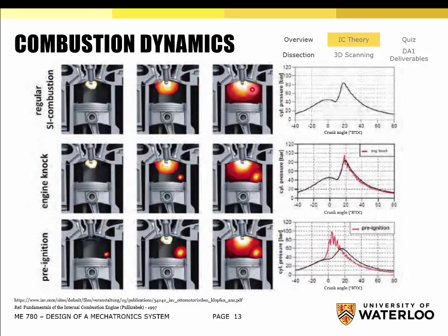But what happens if we have too much temperature, too much pressure, some really poor fuel, or some inhomogeneity in the cylinder? We might have something like this, where there's some rogue event where it's actually igniting somewhere else. Okay, so we've ignited it where it's supposed to with the spark plug, and it starts to increase in pressure and temperature, and what that's doing is it's actually compressing the surrounding fluid too.